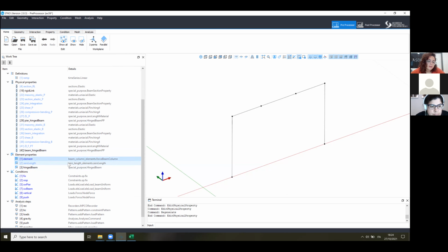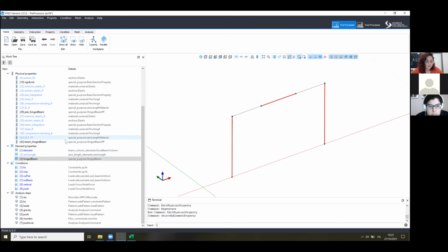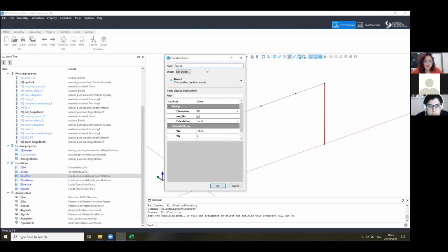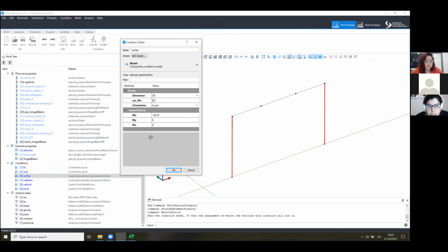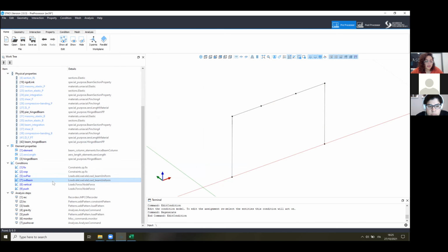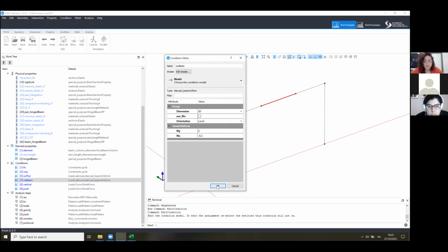Okay, and the same as I did for the beam with shear hinges. In this case, I use the hinge beam and a zero-length element. I have to add an extra element with respect to what I had before. And I apply this to my structure. Same goes here. One thing that I added here was a self-weight that I didn't put in the other model. I should have actually, because it made much more sense to have both with self-weight.